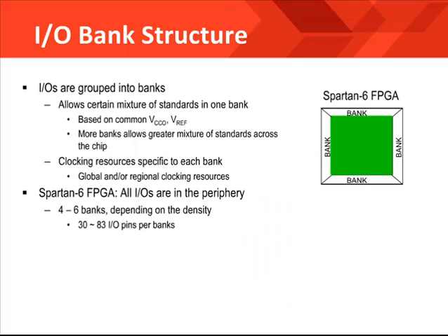The input-output blocks, or IOBs, interface between the FPGA and the outside world. They are shown in this diagram on the periphery of the die. IOBs are grouped into IO banks located on each edge of the device. The IOBs contain registers and some specialized resources, but the main purpose of the IOBs is to clock data in and out of the FPGA. In fact, using the registers to clock data in and out of the device is the fastest way to move data in or out. Besides the registers, the IOBs contain interface logic that is designed to translate the internal voltage domain of the FPGA to whatever I/O standard you're using outside the FPGA. This saves you from having to add all the necessary interface logic outside of the FPGA.